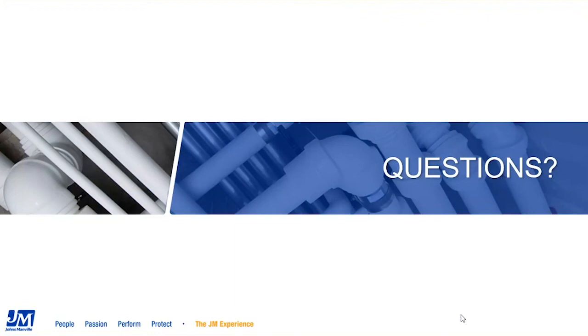I agree, Meredith, and I think with the foil facers, any change in R value because of the gas that it's originally foamed with would be very slow over time, so not much in the way of diminishing R value over time for the long-term thermal resistance.